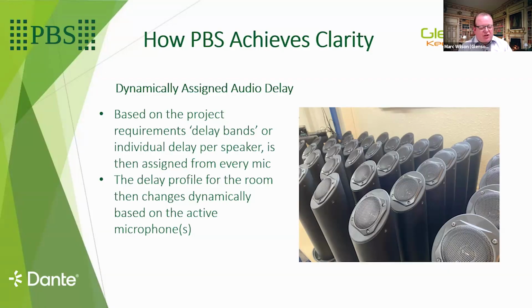So in the main debating chambers, these are typically manually switched, and every time an active microphone is switched, the delay to every speaker or group of speakers is changing dynamically all the time as we're switching microphones. So there's a lot of processing going on to manage the delay between the multiple incoming mics and source speakers for us to maintain and minimize all of the delay within the chamber. Very significant part of the system.